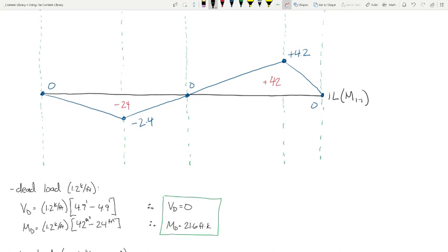And where do I place the point load? At B, at the hinge. And think about what that does to this point. Remember, that's our point of interest. What's the beam going to do? Well, here it's going to smile, but there it's going to frown, right? That's going to generate the worst case frowny face at our point in question. Make sense?